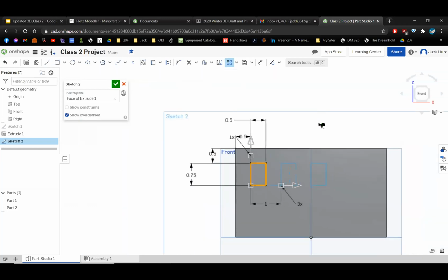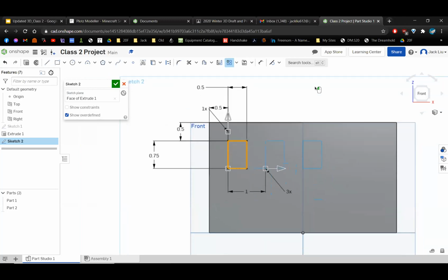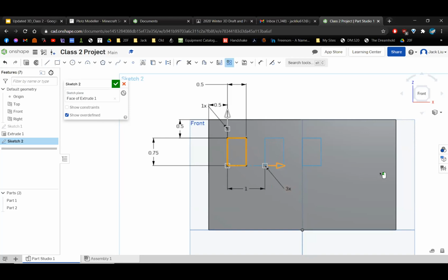So first of all, just to quickly describe what linear pattern means, a linear pattern is just taking a set of edges, a shape, whatever you want, and creating multiple copies of them, kind of in a grid pattern, right? So there's 2 parameters, well, really 4, but 2 different parameters that we can define. How many of them we want and how far apart are they spaced, right? And so this can be where a little bit of math comes in. So let's look at this setup.